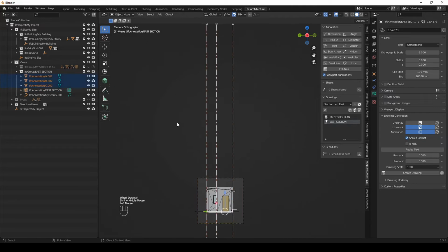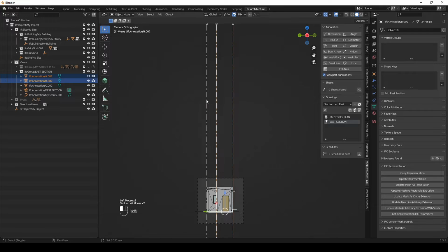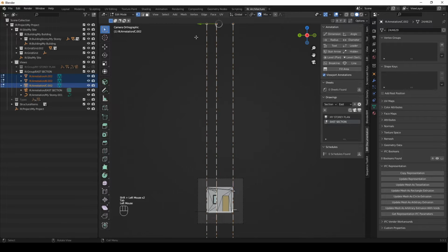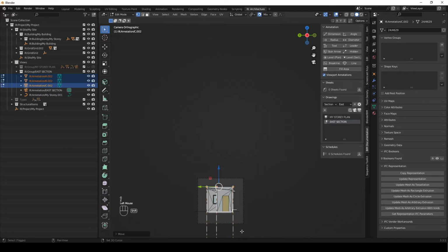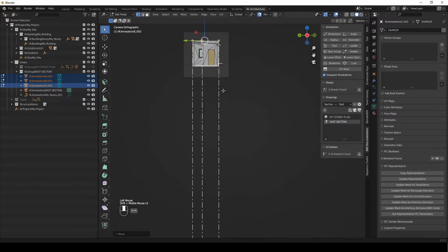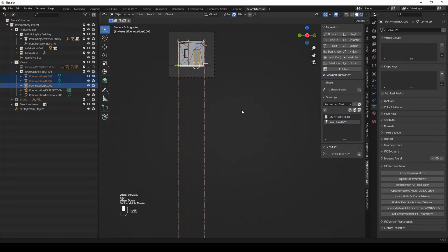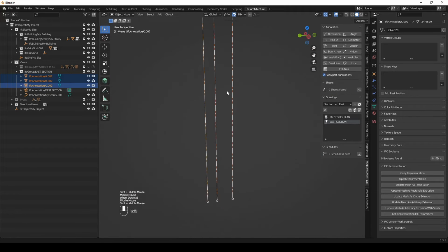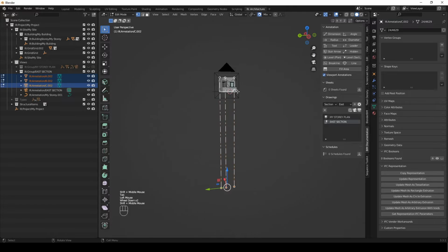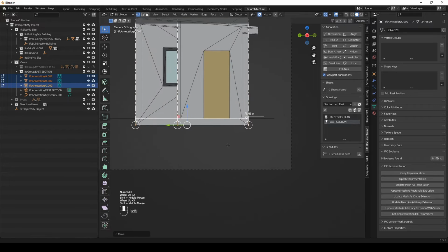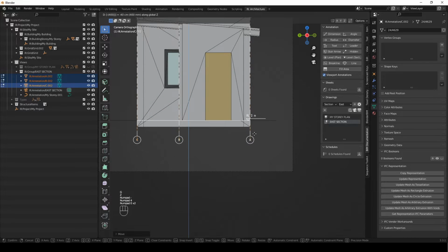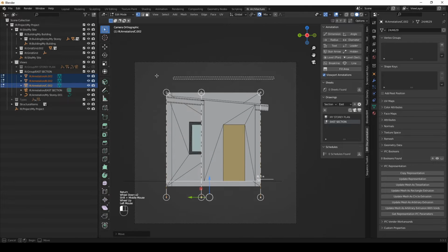And then you can just see our grid lines have not been adjusted, so I'm just going to select them, and I'm just going to say tab. And I'm going to grab the tops there, and I'm going to say GZ, bring them in. And we're just going to snap out of the view so we can just come to the bottoms. And I'm going to say GZ to bring them up. And I'm going to press naught to snap back into the view. And I'm just going to say GZ minus 400. 1 to 50, 400, 500, 600 is a good millimeter spacing. GZ 400, so it's out of the way.